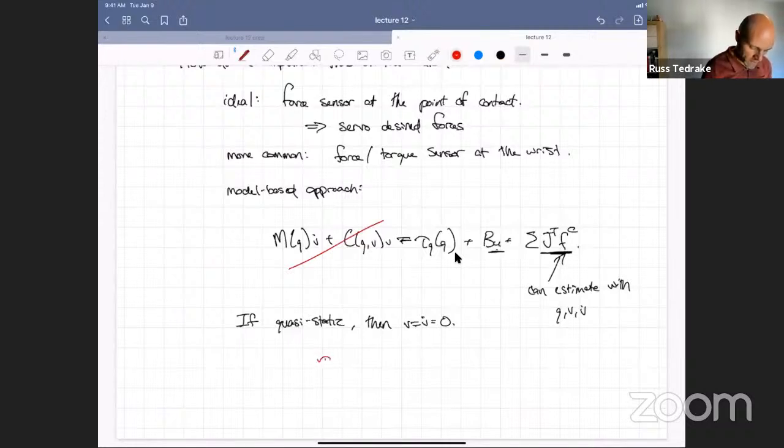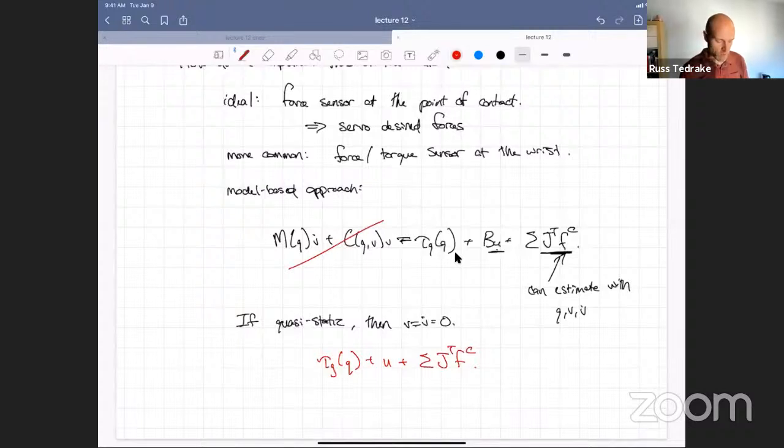Just think about your force balance. And if I'm fully actuated, because I'm just using the gripper, I'll leave the B off so I can command everything. Then this gets us back to what we were doing on the fingers, right? Which was writing u to cancel mg plus the commanded force.